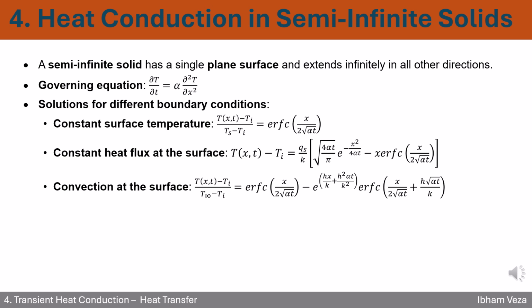4. Focus on simplicity with semi-infinite solids. Sometimes we can simplify a complex geometry. Semi-infinite solids assume one exposed surface, while the rest stretches to infinity, making the math more manageable. You only need to focus on the surface behavior.